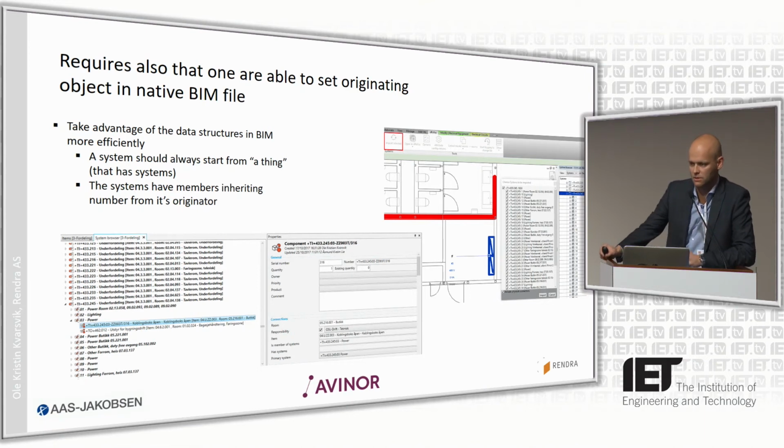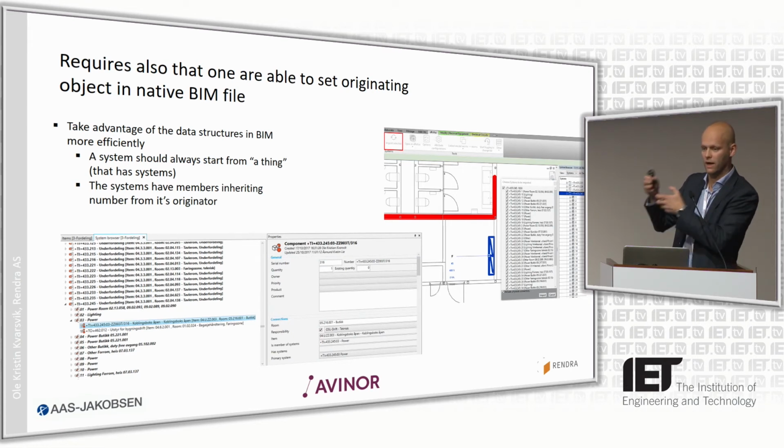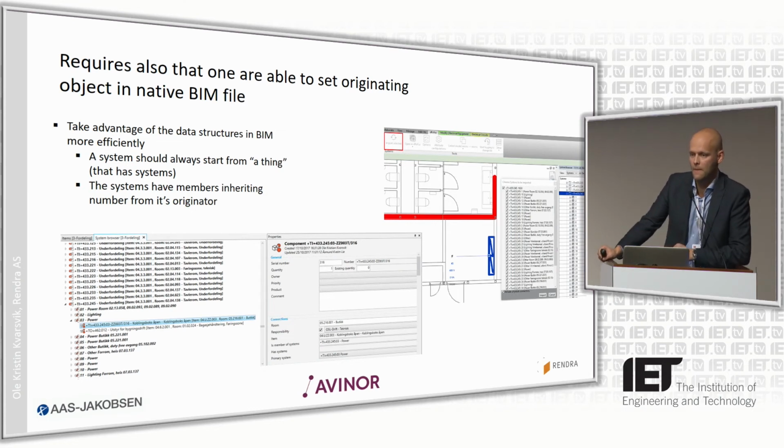the Rofus was mentioned by Bjørnar. This is actually a content management tool. So it means that you can synchronize properties, attributes to different object classes or categories, if you wish, in Revit. And you can synchronize and suck up whatever is in the design file, and you can put something back in the design file. It means that when you have 100 plus different BIM authoring files out there, you can actually manage those things one place.